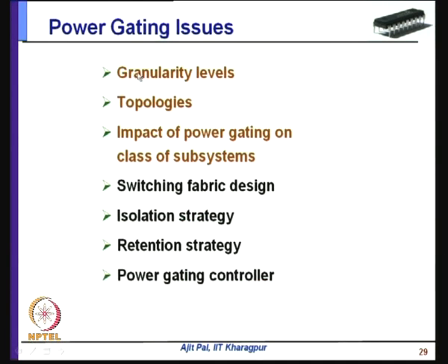very complex, and it involves a number of issues, like at what granularity level it is being done, what is the topology of the circuit, what is the impact of power gating on the classes of subsystems. Then you have to design the switching fabric, you have to use an isolation strategy, and a retention strategy. When the circuit is in standby, you have to retain some of the states, and that retention strategy has to be identified. Then the power gating controller circuit has to be designed. So, these are the techniques which I have discussed in detail in this lecture series.